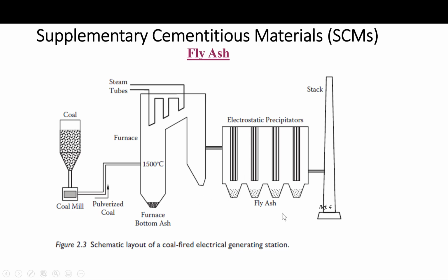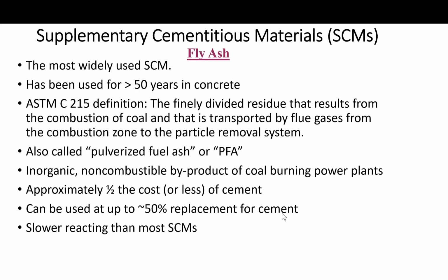Okay. Fly ashes are employed in a variety of construction, and many ready mix companies add fly ash routinely to their concrete. Although their motivation is mainly economic, fly ash is less than maybe half the price of the cement.